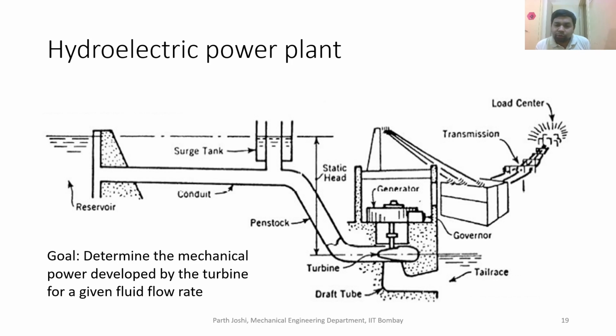Yeah, so you're right. You'll include the turbine, but importantly, we will also include the draft tube, tail race, etc., because some fluid is entering the turbine and some fluid is leaving the turbine. There is some kinetic energy of the fluid that is entering, and there is some kinetic energy, very little compared to the fluid entering, but still some, left in the fluid.